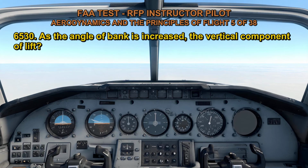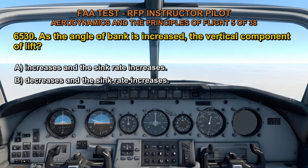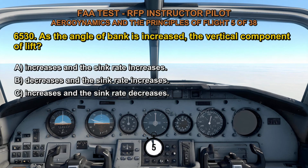6530. As the angle of bank is increased, the vertical component of lift A. Increases and the sink rate increases. B. Decreases and the sink rate increases. C. Increases and the sink rate decreases. The correct answer is B.